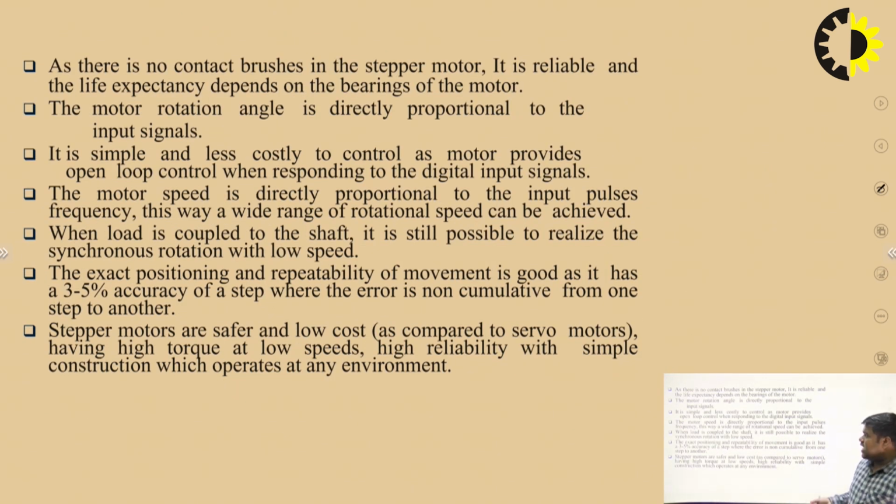On the other side, we will see, as there are no contact brushes in the stepper motor, the reliability is high and the life expectancy depends on the bearings of the motor. The motor rotor angle is directly proportional to the input signal that carries the input electrical pulses as a triggering. It is simple and less costly to control as the motor provides open loop control when responding to the digital input signals. This is the main thing, open loop control system.